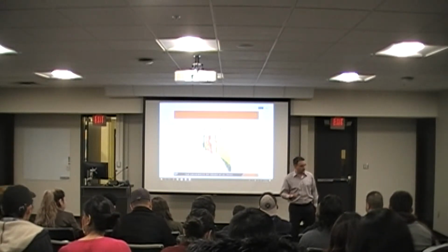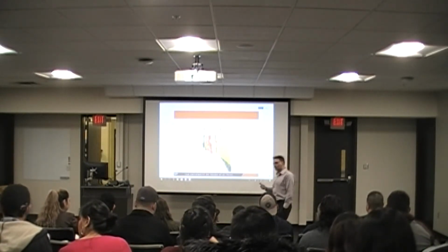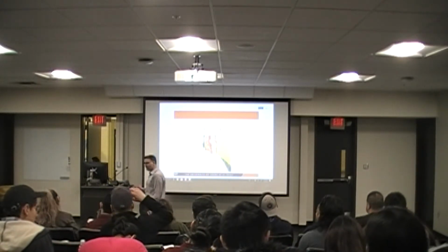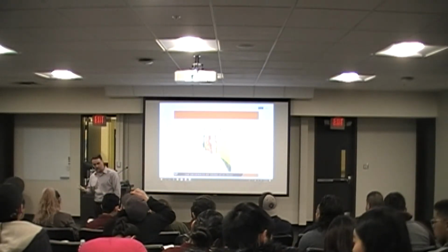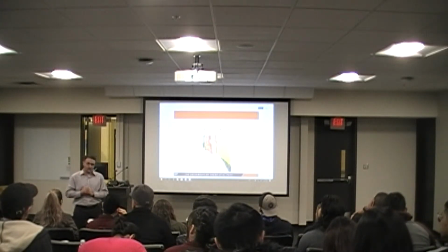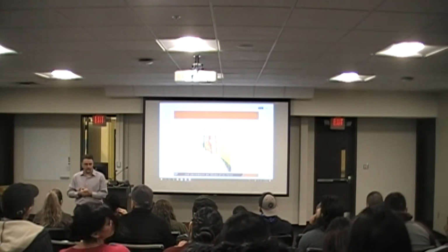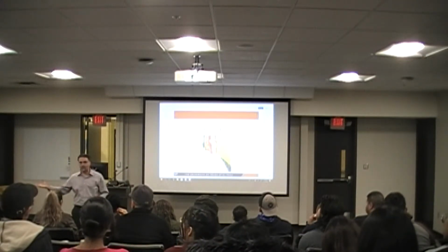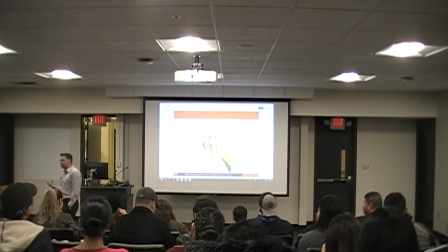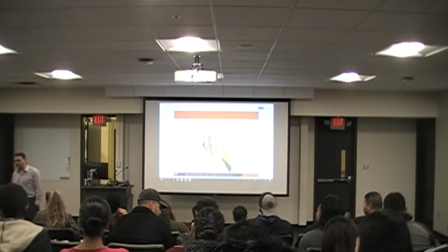Instead of going and talking about, I need a material with extremely low plasticity and with low amounts of fines in it, I want to make sure that the gradation distribution is elongated, I want very good interaction between the particles, I want good friction between the particles, instead of saying all of those, we say, go get me some GW. Right? So that would be the language that engineers will communicate in the field.